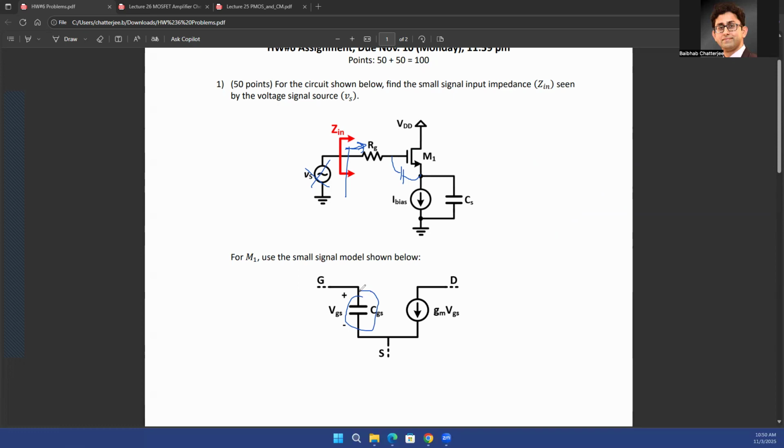Right, or Thevenin equivalent impedance. Let's call it Thevenin equivalent impedance now, because you have a capacitance component. After we figure out the capacitor, do we combine it in series and then parallel with the impedance of the... Yeah, so impedance generally comes in, let's say, if it is series, you just add the impedances. If it is in parallel, you take the parallel combination of impedances.